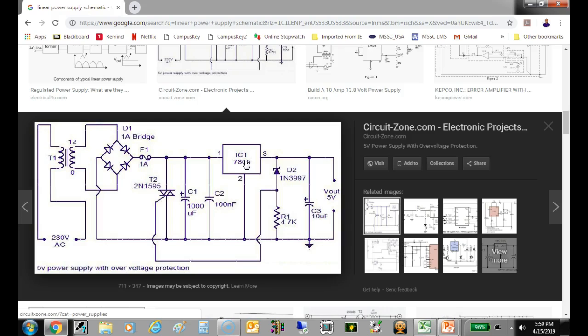Here's Alabama Power on this side. This computer, if I plug this in in Alabama, is a regulated power supply, which means even though my loads are constantly varying in my computer, right? When my hard drive starts seeking, it pulls more current. When I'm using my USB, it pulls more current. I've got a 5 amp USB port on this thing. So instead of getting 100 milliamps like these other ports, this one has the ability to provide 5 amps. If I plug something in here, my power supply would try to drop down, but the regulator keeps it what?